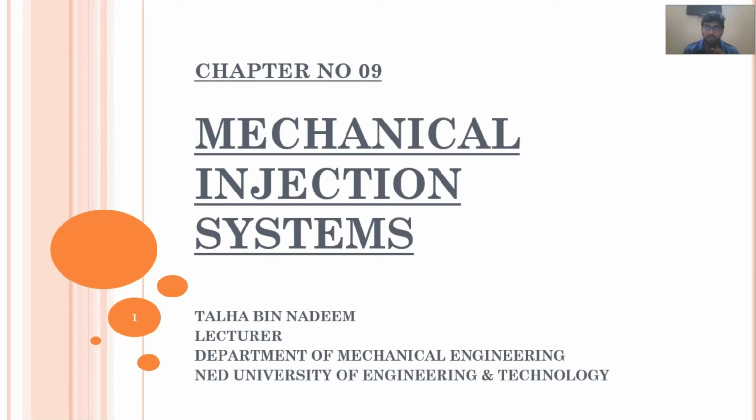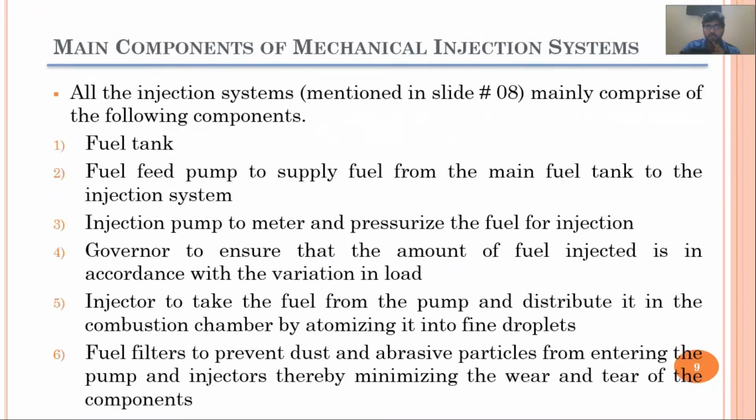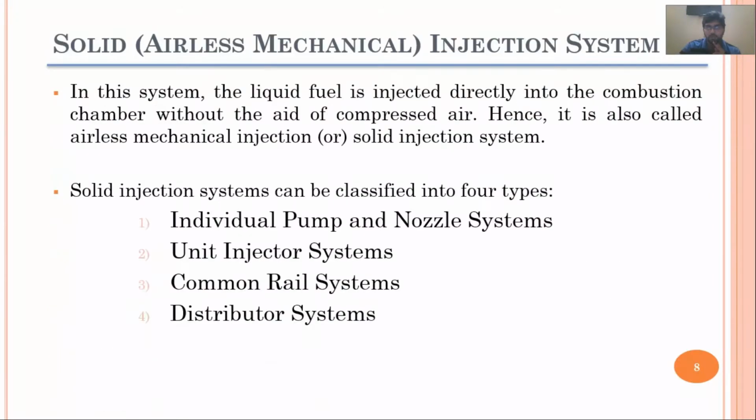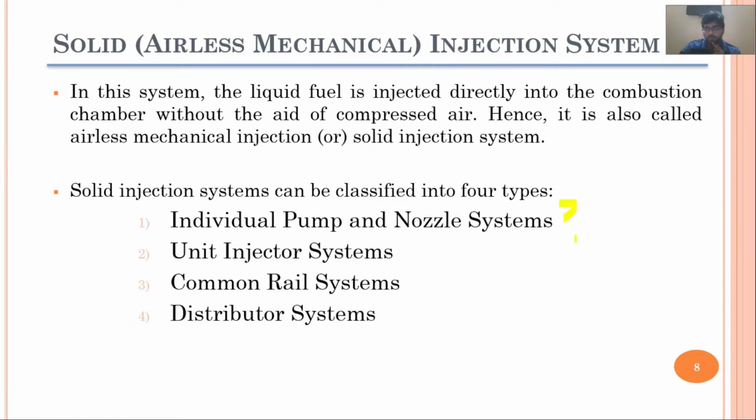So in the last recorded video lecture, we basically studied some of the different arrangements which are most commonly being used in solid injection system: the individual pump and nozzle system, unit injector system, common rail system, and distributor system.